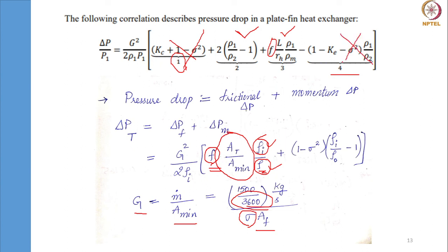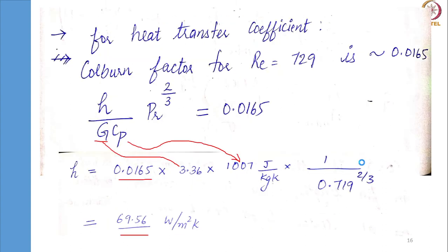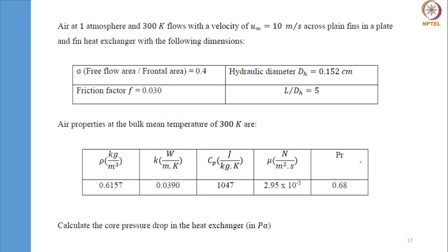So we dealt with these two terms in our previous problem. I'll suggest you take a close look and see. So this expression basically turned into this expression for our previous problem. So I will suggest you take a closer look and see if the same formula can be applied in this problem too. Remember, we want only core pressure drop. So that's the reason we are neglecting the pressure drop due to area contraction and pressure rise due to area expansion.